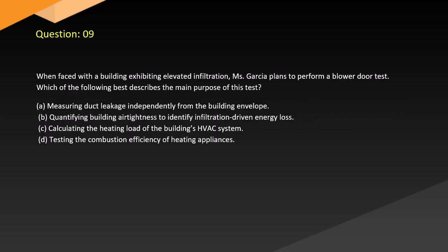Question 9. When faced with a building exhibiting elevated infiltration, Garcia plans to perform a blower-door test. Which of the following best describes the main purpose of this test? A. Measuring duct leakage independently from the building envelope. B. Quantifying building air tightness to identify infiltration-driven energy loss.